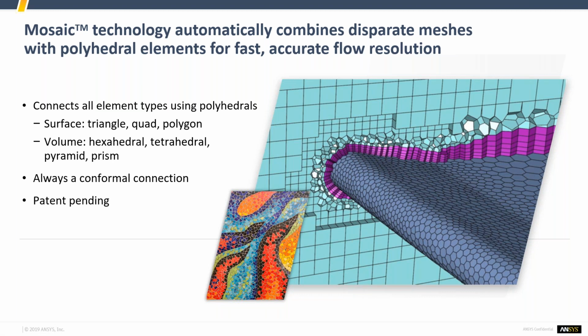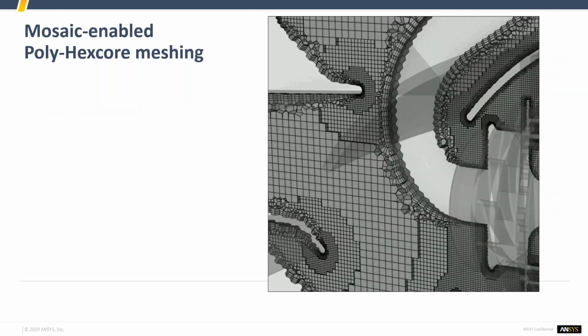The reason for this is the flexibility of doing such a mesh: you can first do a surface mesh with curvature settings or body of influence of what you want to do, and then combine that with a hex mesh in the bulk, which is of course very fast to solve on.